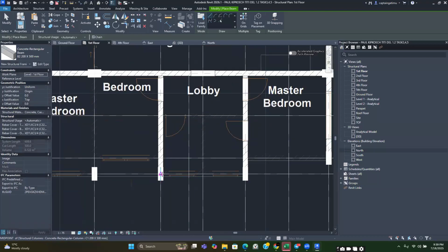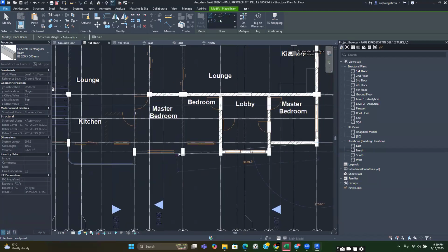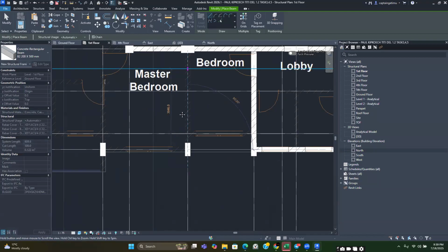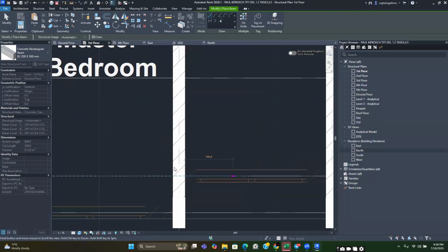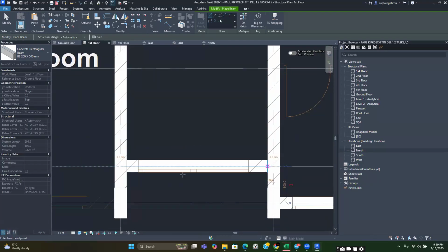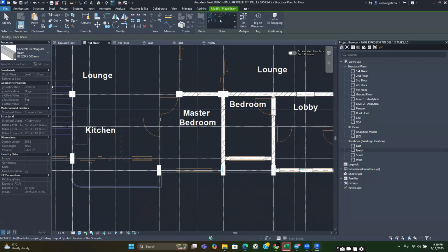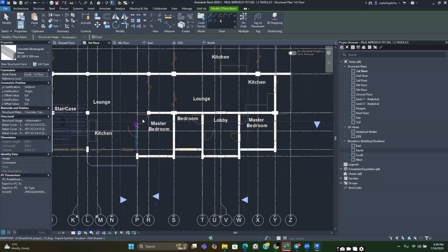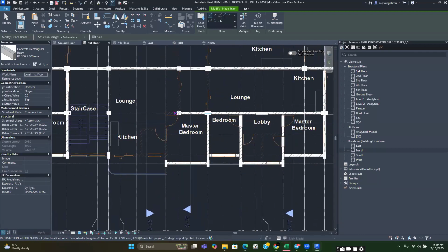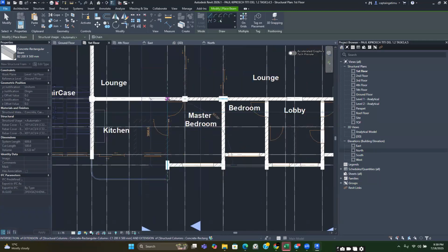So we do that for all the beams. Wherever there's a beam, you place them in this cross section. Then as you do this, I recommend you go through the drawing and identify which cross section is the most common, or which cross section has been used the most, and select it for this modeling, so that you don't have to make a lot of changes later on. Okay, then let's do this there.